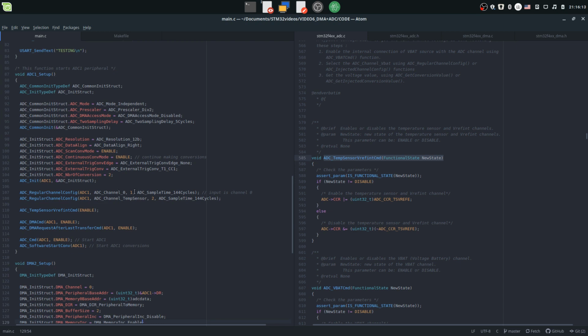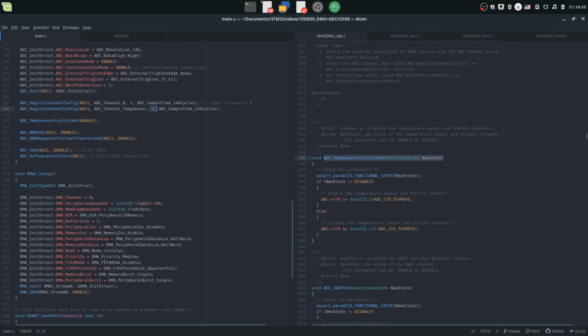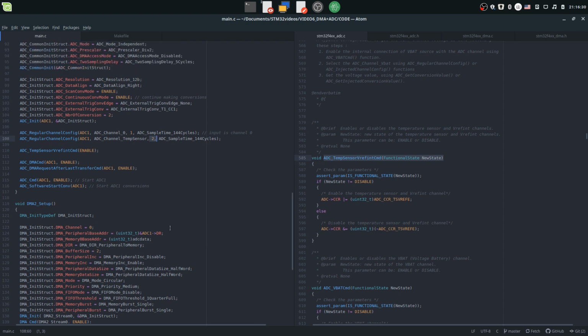The ADC converts the first one, the ADC is gonna read it and put it in the memory location ADC data. It's gonna increment its number. Then we're gonna read the second one, DMA copies it, and puts it into the second part of this array, and over and over like that.